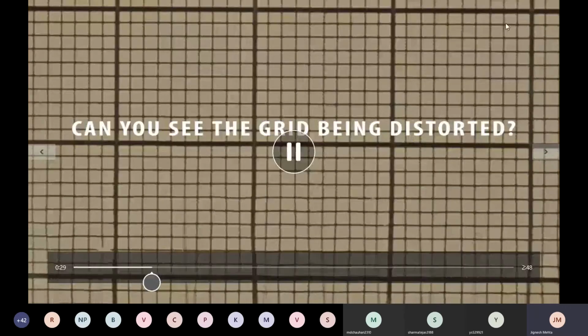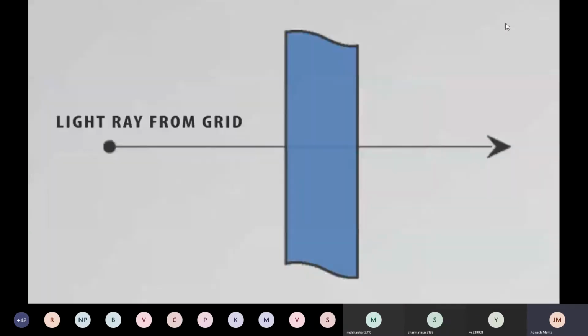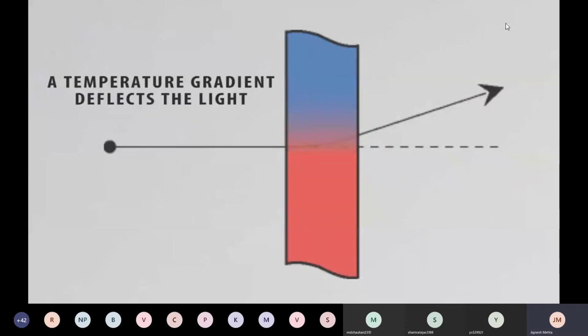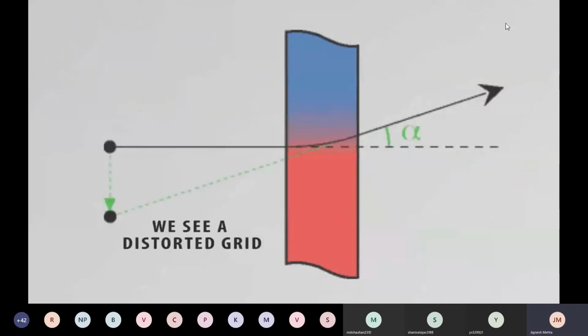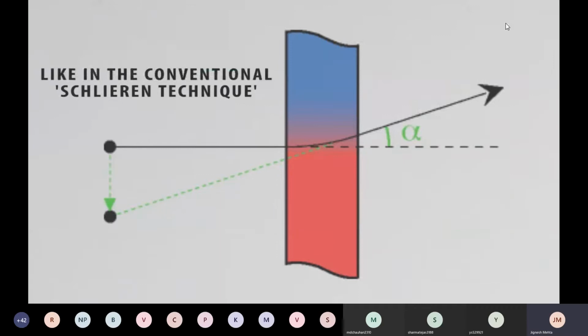So here you are not able to see the vapor bubbles, right? In spite of the delta TE existing, but this is natural. This is showing natural convective boiling. So natural convective boiling was not obvious because there was no bubble generated.